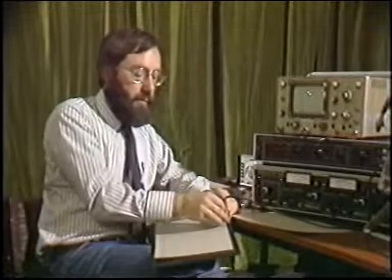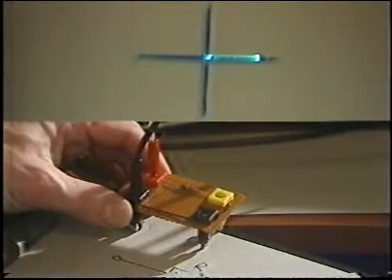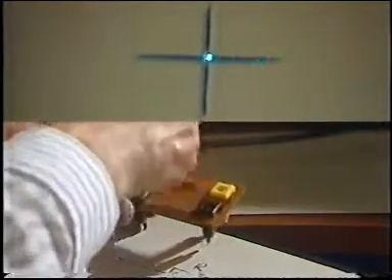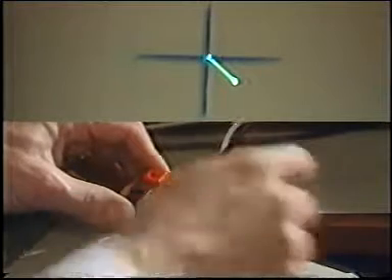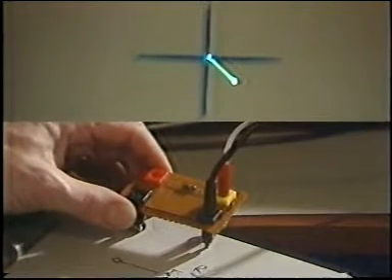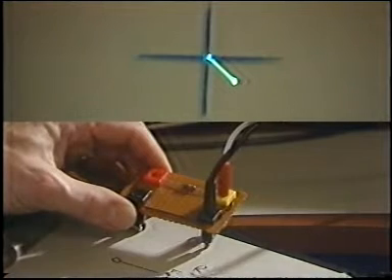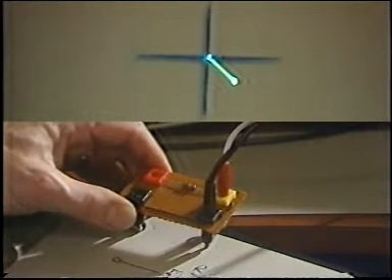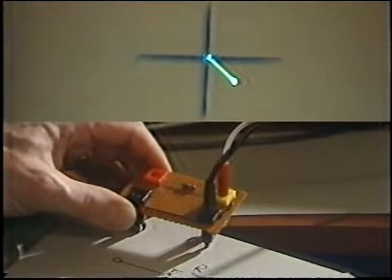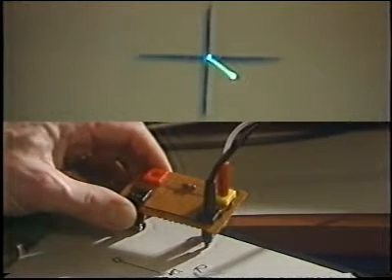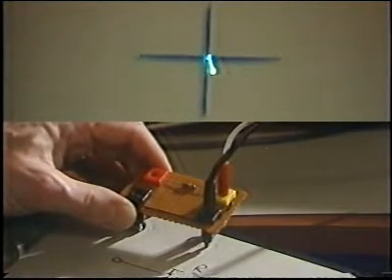First of all, the reference phasor taken across the input. There it is on the screen, projected along the phase reference axis. Now, the phasor of the capacitor voltage is lagging the reference by roughly 45 degrees because we are round about the cutoff frequency of the circuit. I'm now going to increase the frequency. The signal across the capacitor will reduce in amplitude, the phasor gets shorter, and the angle is increasing towards 90 degrees.